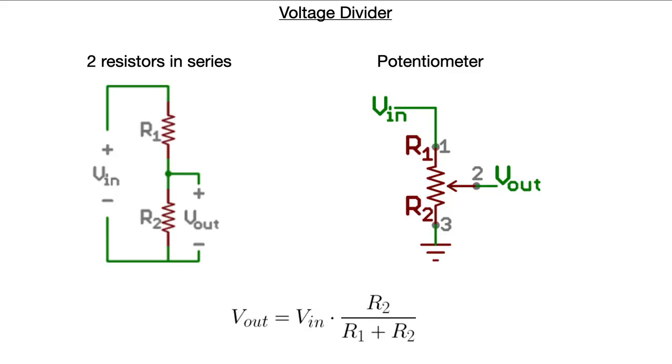The one that I built, and the one which is similar to the one from Edmund Scientific and Radio Shack and GE, operate on the idea of voltage dividers. And a voltage divider in its simplest form is just 2 resistors in series, like this. And if you tap the circuit and read the voltage between the 2 resistors, the output voltage is different than the input voltage by the ratio of the resistors.